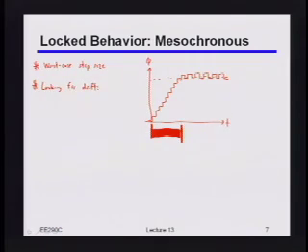So what do you want to do for that step size? You want to make it big, small, medium? Yeah, you want to make it small, right? Because basically the size of that step, the bigger it is, the faster I can track things, right? The less time it will take me to do that initial lock.